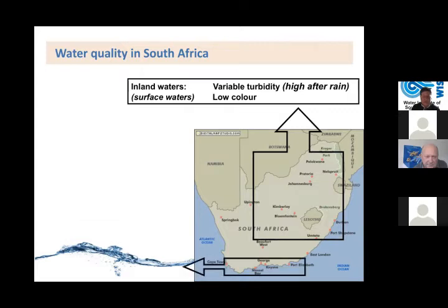but there are a lot of new technologies coming into the market now. In the southern coastal zones, indicated there up to Cape Town, you may have seen the river waters have a yellowish to brown color, the natural water. And that's mostly organics in the water, natural organic matter, or NOM, that gives rise to high color. Now, this color is not necessarily a problem or a health risk if you ingest that water, but there are other secondary risks.